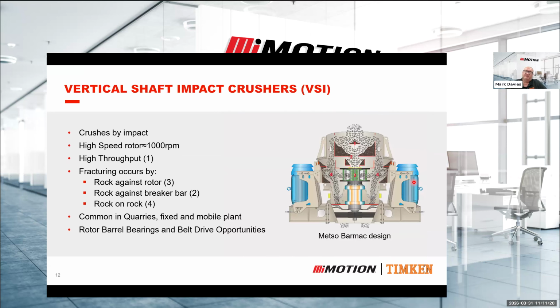A different type of crusher is an impact crusher. As I said before, it is the vertical shaft impact crusher, the VSI crusher. This is a Metso Barmac design. These are one of the first ones that came out. And the way it works is it's rotating through this barrel here. The shaft is rotating and turning this impeller at high speed, about 1,000 RPM.